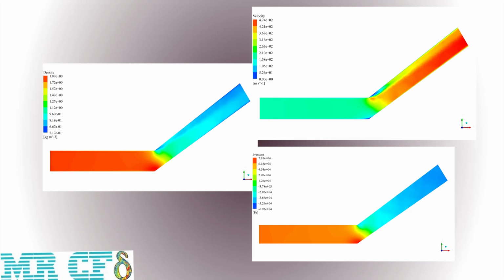On the other hand, the Y+ value is recommended to be under 1, but we've used a tetrahedron coarse mesh grid that couldn't satisfy that criterion. As a result, a gradient adaptation option was used to refine the mesh in zones with a high Y+ number. As shown in contours, pressure drops about 120 kilopascals during the pass and causes extreme variable distribution through the pipe.